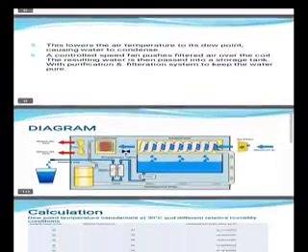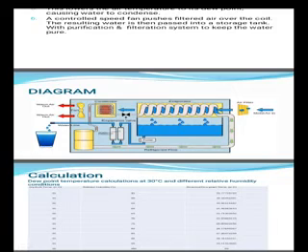This is the diagrammatic view. Here we have converted the vapor content into water. This water is stored in the storage tank. Now, due to the heat taken in by the evaporator, the refrigerant in the coil converts from liquid to vapor form. Here, the temperature increases. This vapor of refrigerant is then passed to the compressor, where the compressor compresses the vapor, and the pressure of the refrigerant increases.